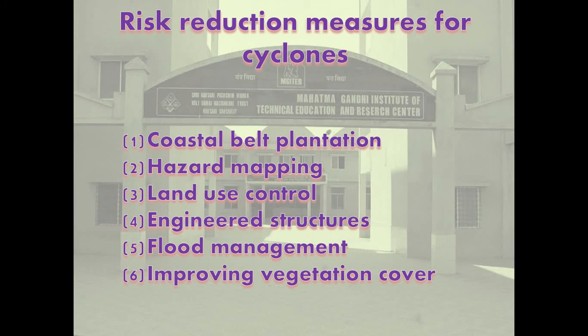For example, avoid large overhangs of roofs, and the projections should be tied down. A row of planted trees will act as a shield. It reduces the energy. Buildings should be wind and water resistant. Buildings storing food supplies must be protected against the winds and water. Protect river embankments. Communication lines should be installed underground. Provide strong halls for community shelter in vulnerable locations.